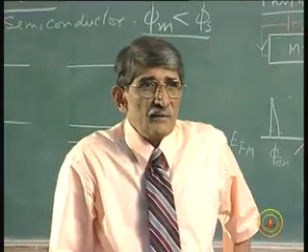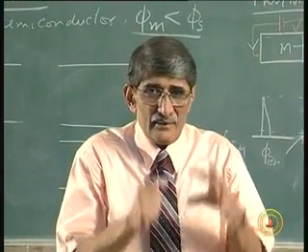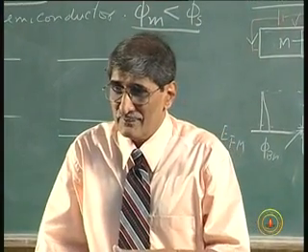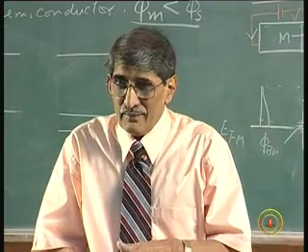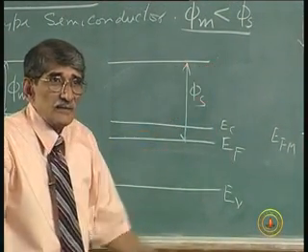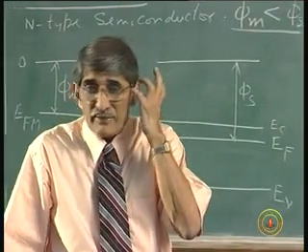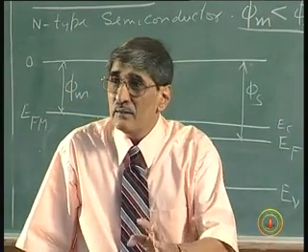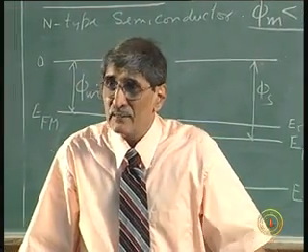If you want to make ohmic contact, choose a material whose phi m is smaller. It need not be less than phi of s. So long as it is closer and closer to that phi of s, you will have closer and closer to ohmic contact, otherwise rectifying.